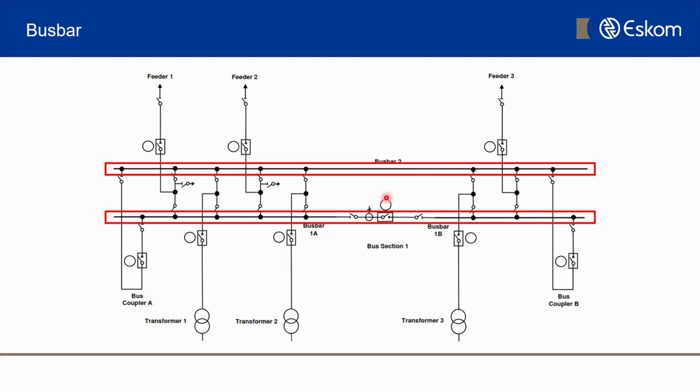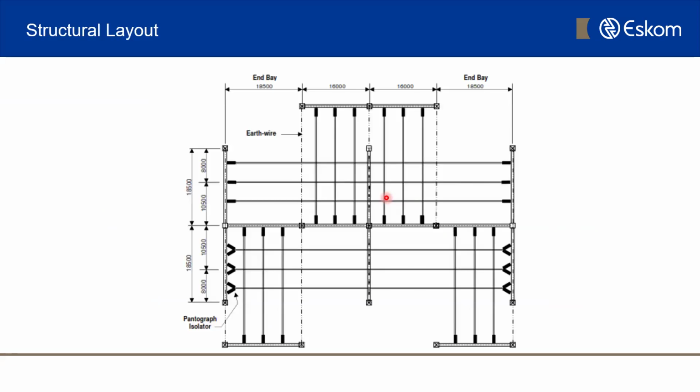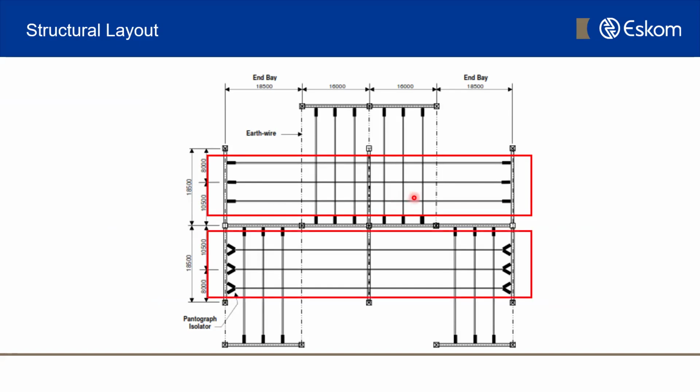If we move over to the next slide, again, you will see if we highlight the areas, there's two areas, that's the bus bar, and the next area below that is a bus bar as well. So these are three phases, as you can see, three lines running across each section. So each phase is labeled blue, white, and red, or sometimes blue, yellow, and red. It depends on where we are looking at this in the system.